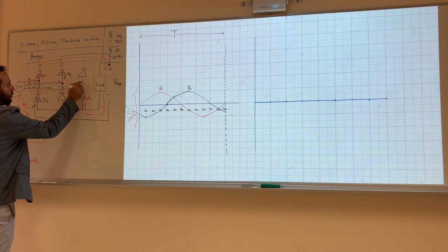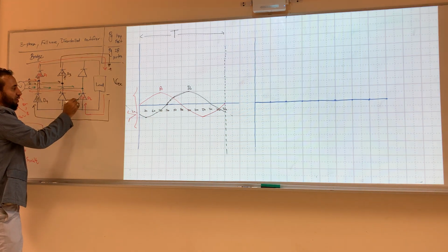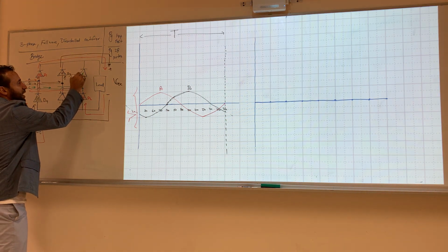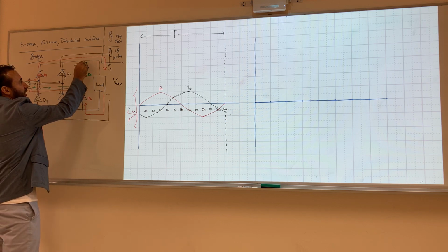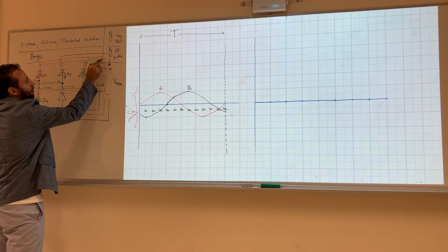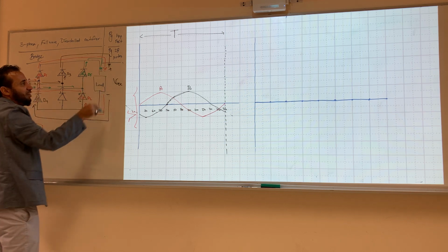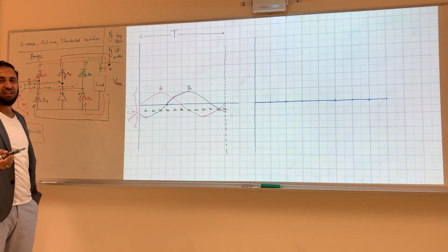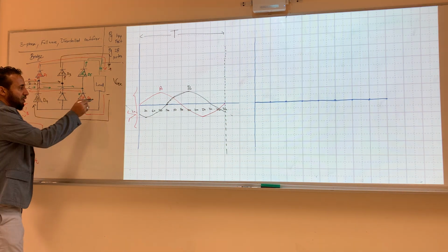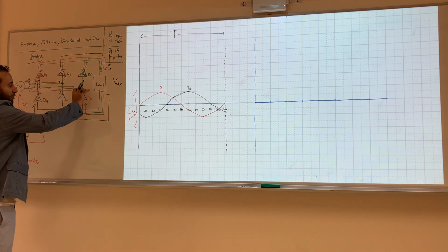And this one here, so as we said, this line will be fully charged, so this will be an open circuit because the polarity will be flipped. And now this one here, this diode is diode number 5. And now the current is going here and coming here. So you can see, guys, that this current, and this current and this current come into the load from the same direction. Okay, and then we will go out. As we said, this will be an open circuit.